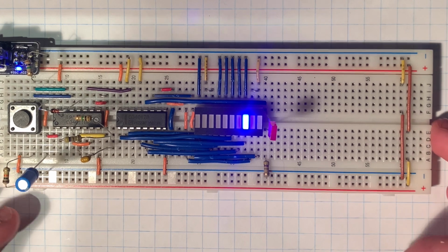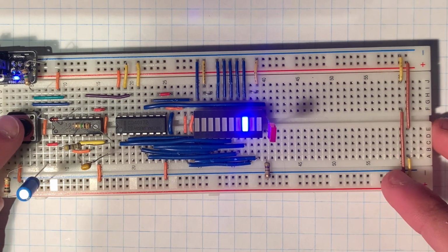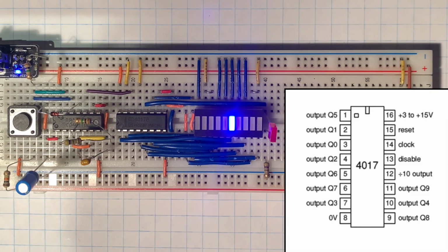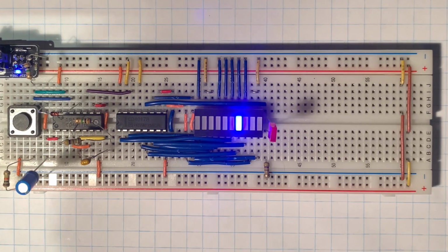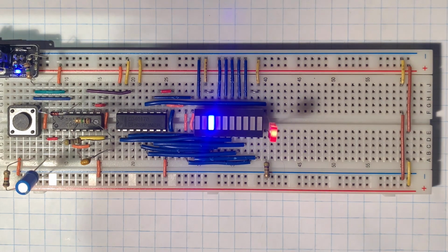To see the result, you plug in a 10-segment LED bar graph, where each LED is connected to an output. The connection is ordered from smallest to biggest numerically, left to right. The product will make an LED bar graph appear to count from left to right. The divide by 10 pin completes a full high-low cycle every 10 times the clock signal input creates a full cycle. This can be used to create multiple digits in a counting circuit.